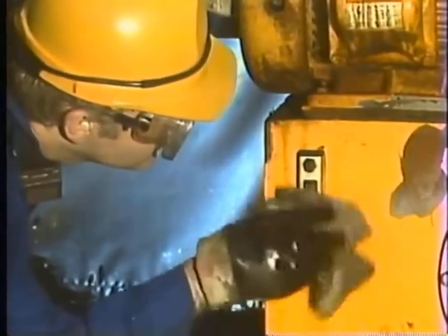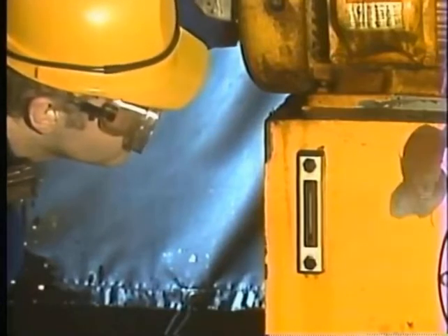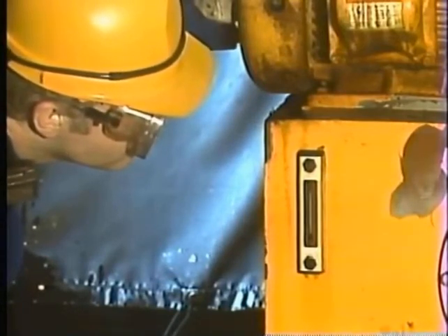Maintaining the proper temperature of the fluid in the reservoir is also important for effective system operation. In this example, the operator checks the fluid temperature on a thermometer within the sight glass. Significant changes in fluid temperature can affect the viscosity of the fluid. Viscosity can be thought of as the measure of how thin or thick a fluid is. Improper fluid viscosity can result in problems such as sluggish actuator operation and inadequate lubrication of moving parts in a hydraulic system.